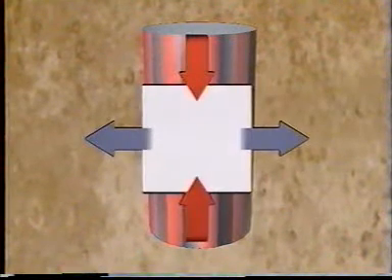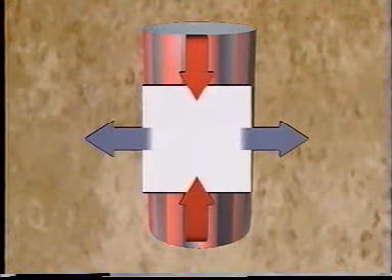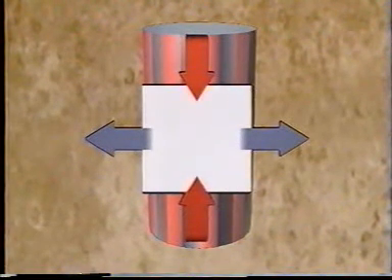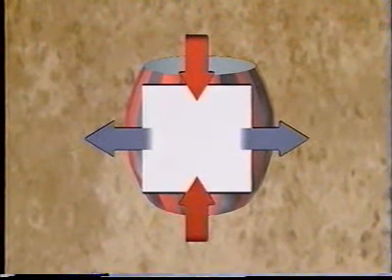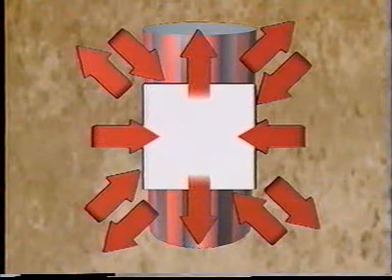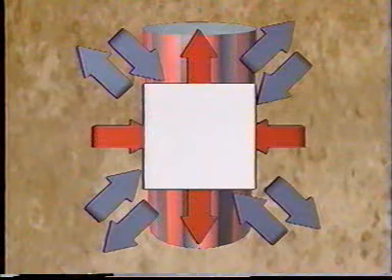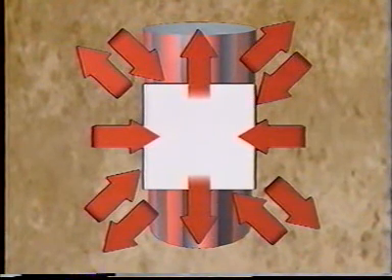By turning the diagram 90 degrees inside the cylinder, the arrows now show a compressive stress applied at the ends of the cylinder. As the compressive stress is applied, the cylinder tends to bulge outward from the resulting tensile stress. The tensile stress component is shown perpendicular to the compressive stress. The direction of shear stresses can also be visualized in the free body diagram. Shear occurs at a 45-degree angle to the axial tensile stress and the transverse compressive stress. There are two sets of shear stresses, each perpendicular to the other, diagonally between the normal stress directions.